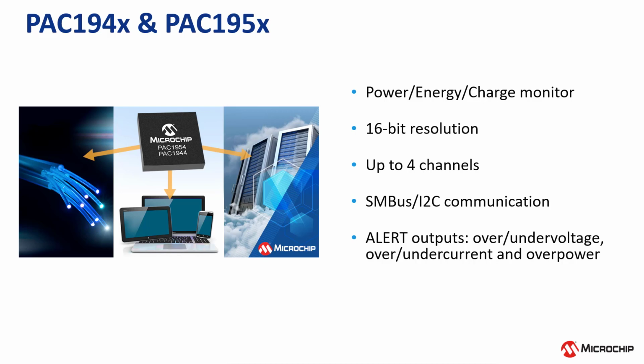Bus voltage, sense resistor voltage, and accumulated proportional power are stored in registers for retrieval by the system host or embedded controller, CPU, MCU. The sampling rate and energy integration period can be controlled over SMBus or I2C. Active channel selection, single-shot measurements, and other controls are also configurable. The PAC devices use real-time calibration to minimize the offset error. No input filters are required for this device.